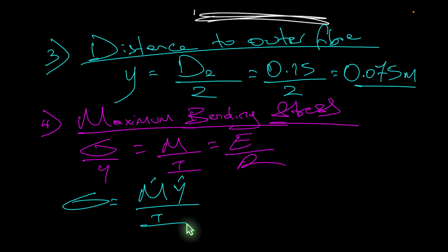Now, the other two variables in the formula that we have not yet mentioned are E, which represents Young's modulus, or the modulus of elasticity of the beam's material, but we're not going to use that in this question because we didn't get that value. And the other variable is R, which represents the radius of curvature of the neutral layer of the beam due to the bending moment. But again, we didn't get that, so we won't use it in this question.